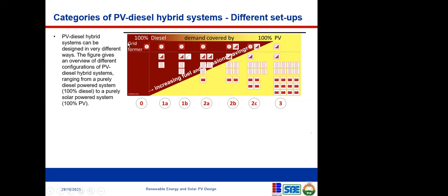Now, what you will notice is that as you keep moving, you keep increasing the solar panels that are required, and you keep increasing the batteries. So for you to completely eliminate your generator, you will need a heavy battery storage system. And that costs a lot of money. And these batteries will not last forever. Okay. Best quality battery and well maintained, I mean, best quality of them, maybe 10 years. Yes, maybe. Okay. I'm talking about lithium ion batteries. Maybe 10 years. If you're talking about lead acid battery, maybe 6. I mean, well maintained. Okay.